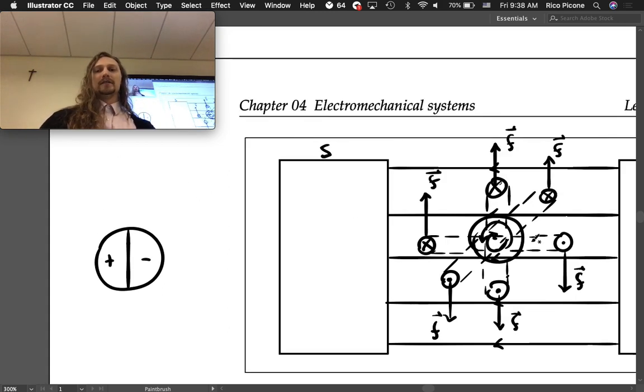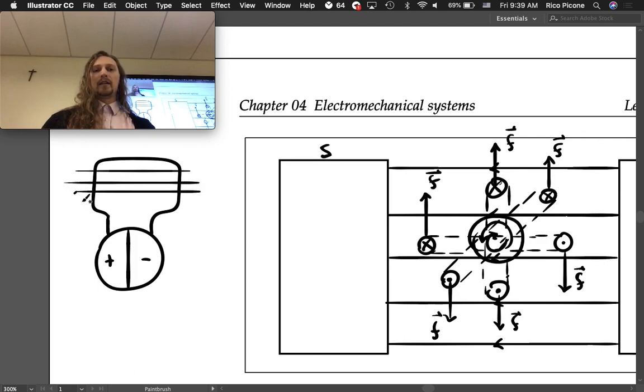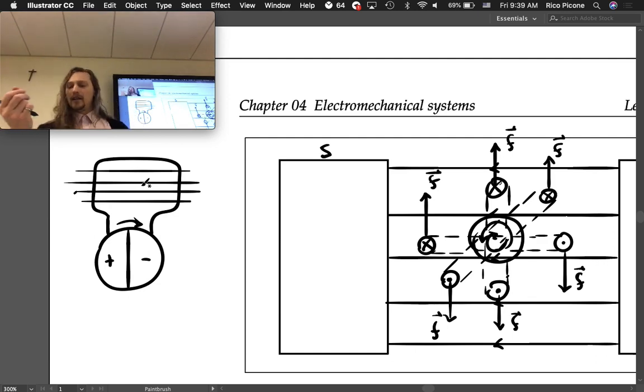And the armature, the wire loop that we have in there, can connect up to this rigidly. So I'll show us sort of a 3D view of it, where we've got the armature going out into the field, and then connecting up to this disc. Okay, and this disc, this commutator, is going to have some sort of mechanical support that holds it in place, and it's going to rotate with the armature. So the armature and the commutator will rotate together.